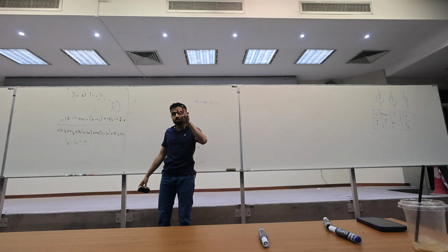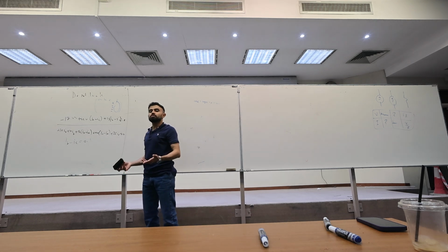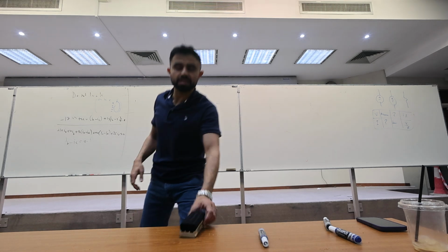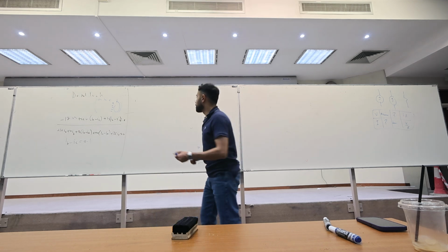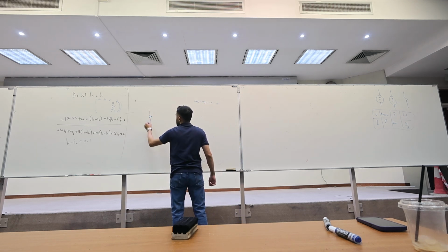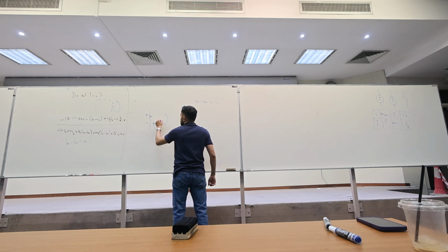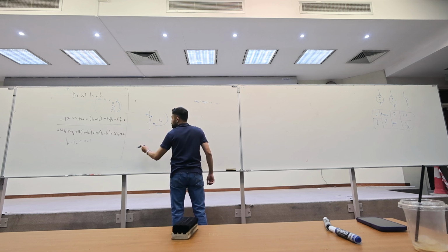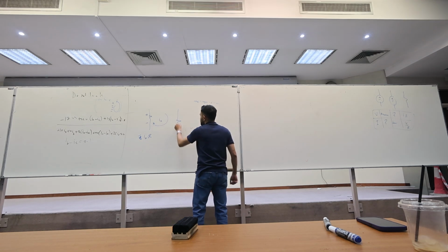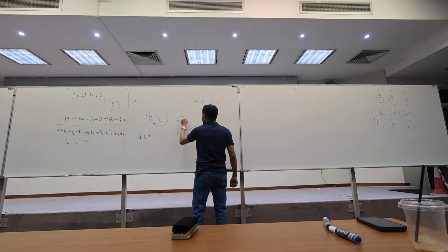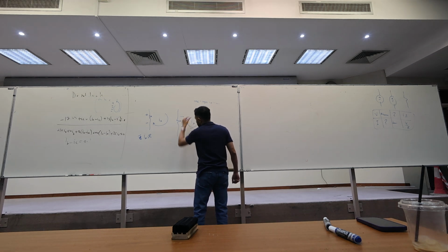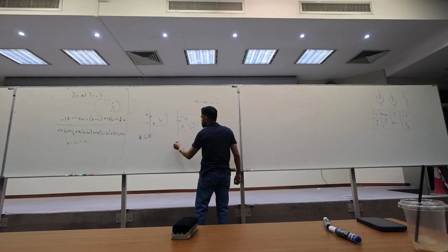Try, you have to solve it. The quiz, what we had in the quiz is problem 8 in the homework. We had a resistor here, right? We said plus minus and we had IA here. So what's the voltage? Voltage rise or voltage drop? Rise. IA times R. It enters from the positive. We have to put a negative sign. If I put it that way, minus and plus, IA, then when we do a KVL, it's voltage rise or voltage drop?